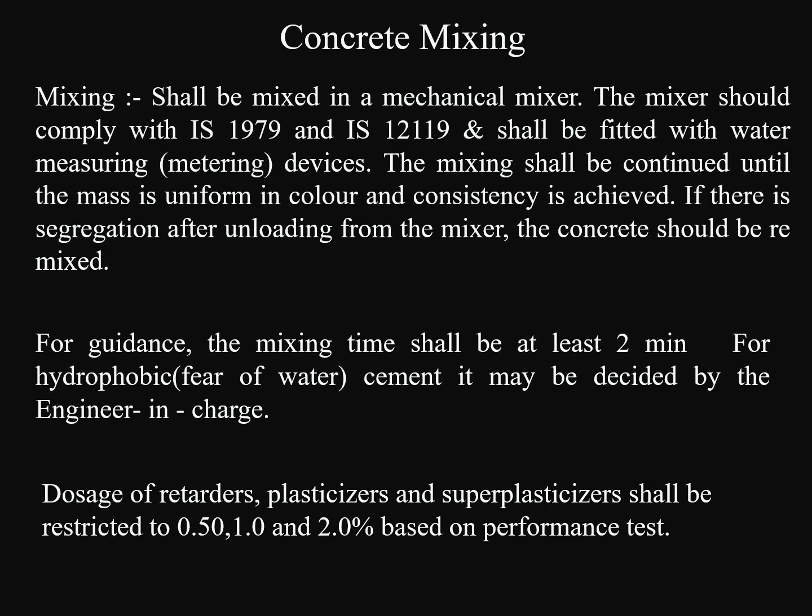Concrete mixing. Concrete shall be mixed in a mechanical mixer. The mixer should comply with IS 1979 and IS 12119 and shall be fitted with a water measuring or metering device. The mixing shall be continued until the mass is uniform in color and consistency is achieved. If there is segregation after unloading from the mixer, the concrete should be remixed. For guidance, the mixing time shall be at least 2 minutes.